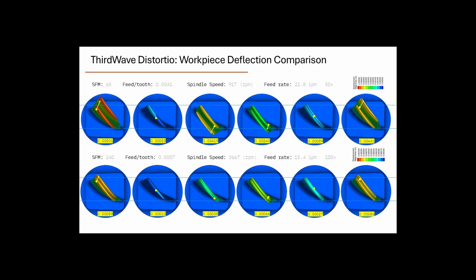And so what we end up with is, if we're taking off a significantly smaller amount of material from the titanium, the forces are reduced significantly. In fact, in order of magnitude, we went from 10 thousandths to about 5 thousandths here. So you can see that the forces are reduced. And to show the distortion more, we add a multiplication factor. So this is at, I believe, 50x, and this is at 100x.